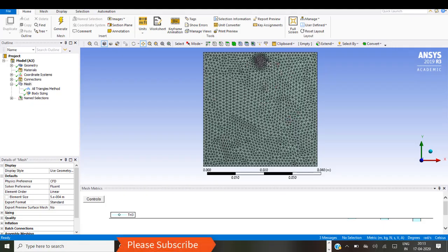So this is the mesh which I have considered. It is very crude because I just want the simulation to run very fast, since it is a triangle simulation and will take more time. You need to refine it in a very good fashion, or else the results we get will not be accurate enough. As this is for demonstration purposes, I think this would be sufficient.